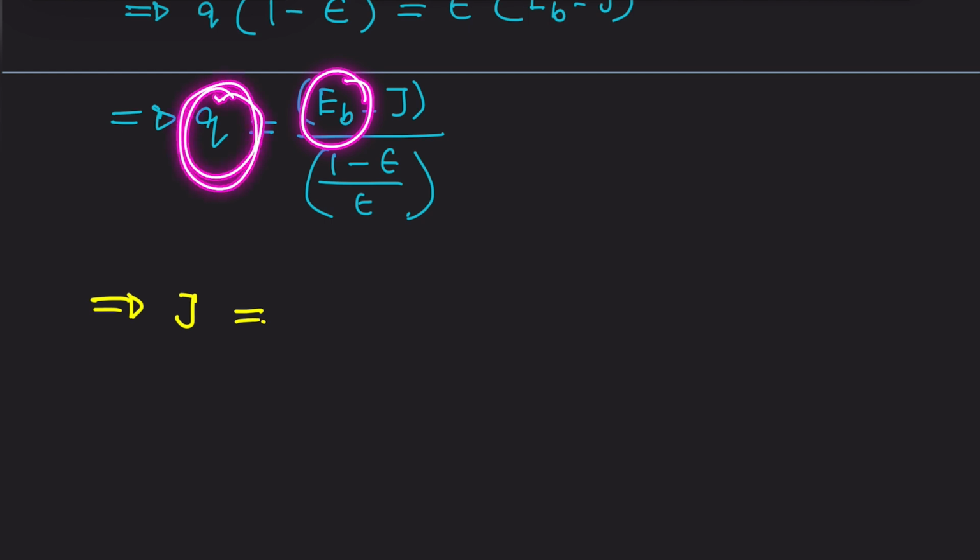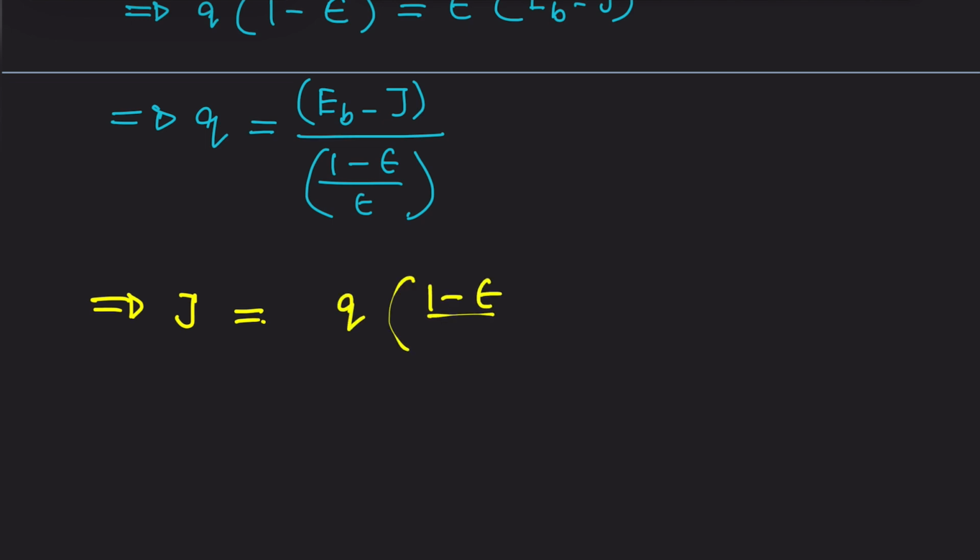In any radiation heat transfer problem regarding enclosures, we need to find the temperature of a surface, which is governed by this term E_B, and we may also be asked to find the heat flux, which is nothing but this. So that is why we don't need this J radiosity, and that is why I will be writing J in terms of Q and E_B.